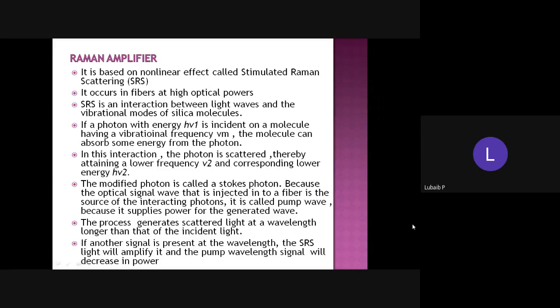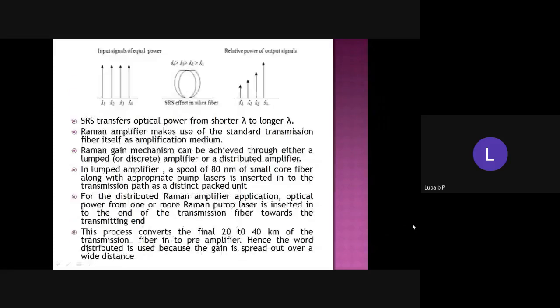If another signal is present at that wavelength, the stimulated Raman scattering light will amplify it, and the pump wavelength signal will decrease in power. You can see in the figure the input signals of equal powers having different wavelengths lambda 1, lambda 2, lambda 3, and lambda 4.